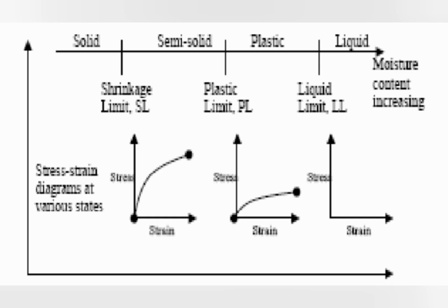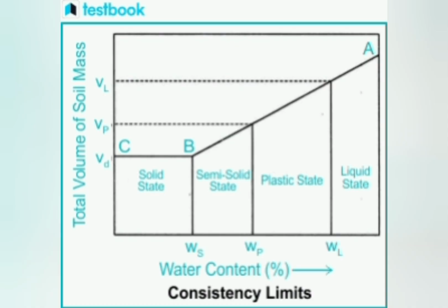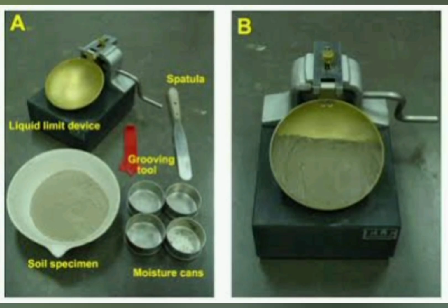The difference between these two values is the plasticity index, PI. The PI is a direct measure of the soil's plasticity. A high PI indicates a clayey soil that will expand when wet and shrink when dry, posing a major risk to foundations. A low PI indicates a silty soil. These simple tests are incredibly powerful. They tell us if a soil is a fat clay, CH, a lean clay, CL, a silt, ML, or something else entirely. A pro tip for foundation design: a high plasticity index is a major red flag for potential differential settlement and requires special foundation considerations.